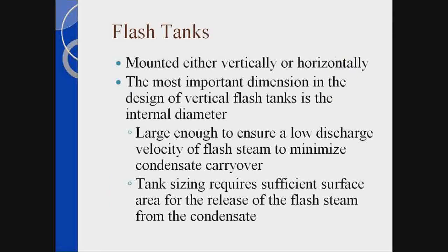Tanks can be mounted vertically or horizontally. The most important dimension in the design of a flash tank is the internal diameter. It's large enough to ensure low discharge velocities of flash to minimize condensate carryover, and there's enough surface area to release the flash from the condensate.